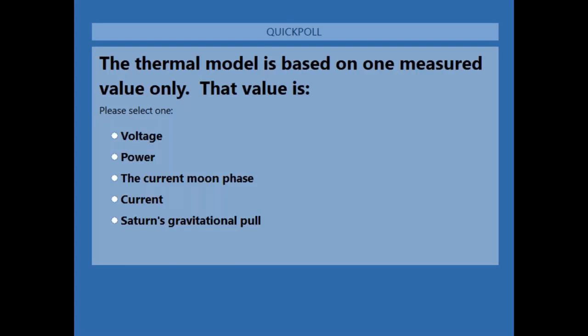And what I'm trying to allude to here is that the thermal model, as advanced as it is, is a one-dimensional means of protection. It only looks at one aspect of the power flowing into the motor.